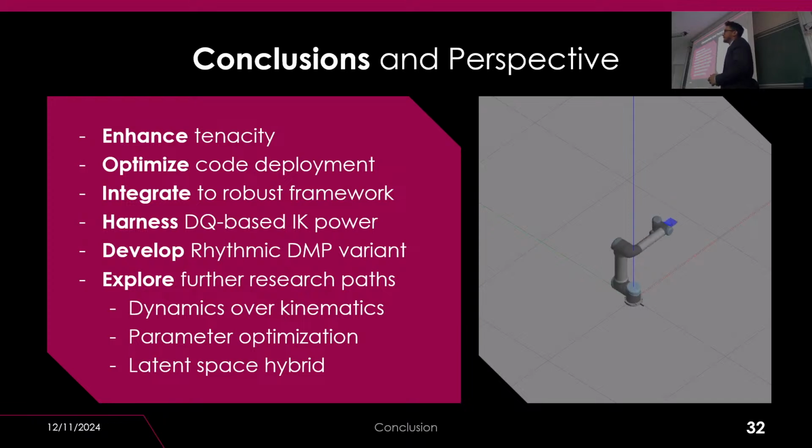I absolutely agree. And even migrating to hyperdual quaternions and dynamics, we could represent, instead of the twist, the wrench, which would be effectively dynamic information embedded as well as the trajectory.